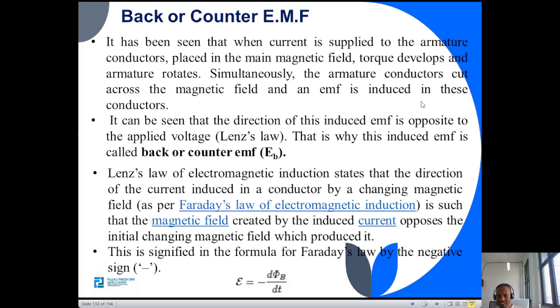Now, if it is a generator, we are directly interested in the induced voltage. In case of the motor, torque is created and the motor is rotating. Even though we don't want that induced voltage, it is inevitable to get induced voltage inside the motor. We call that back EMF. Of course, we need this back EMF. It has very significant importance. We will come to it later. So it can be seen that the direction of this induced EMF is opposed to the applied voltage.